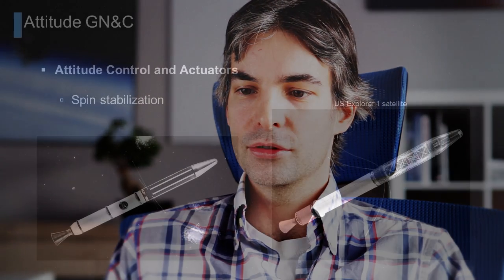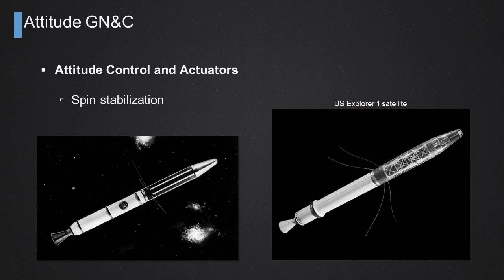Unfortunately, due to mechanical energy dissipation through these flexible antennas that you see on the diagram here, the minor axis of rotation is not a stable axis of rotation anymore. And in fact, after a couple of hours of spinning the satellite about this axis, due to the mechanical energy dissipation, it ended up in a flat spin about the major axis of rotation.